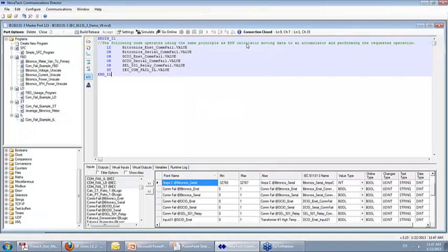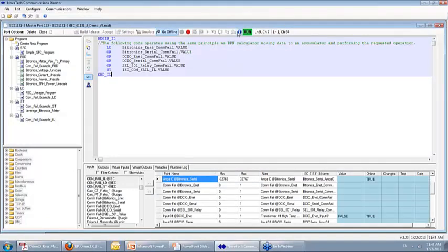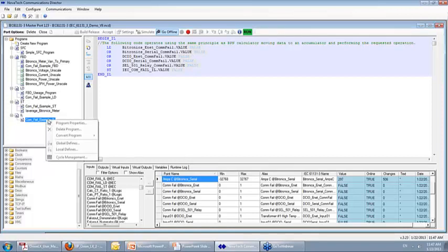I will continue online, and we'll see on the right-hand side of the run bar, or the status bar, there is a run indication indicating that each one of the instructions is being executed. The execution rate we've set for 500 milliseconds, and on the right-hand side, if we highlight each one of the logic packages, we would see that there's a cycle management grayed out